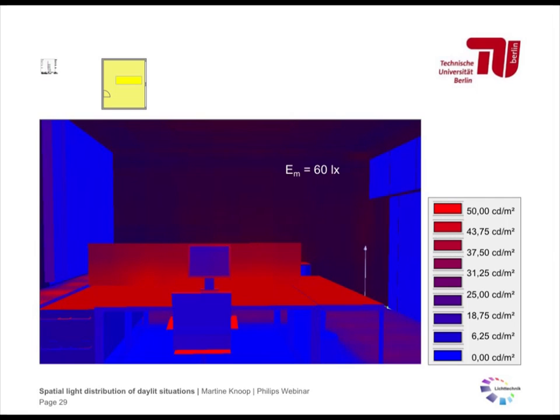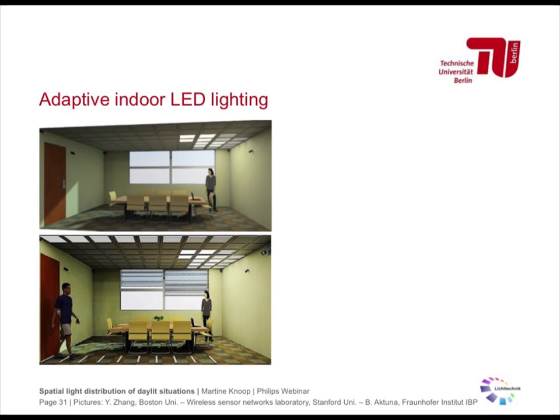I see on the market an advance of adaptive interior LED lighting solutions, or maybe not on the market, but definitely in research. And adaptive interior lighting solutions might really change this. So just keep in mind that if you have directed lighting, the luminance of the walls changes as well. So we have adaptive indoor lighting here. This is an example of it, and it shows that lighting is only used at areas where there are activities. So we have a general lighting level, and additional lighting is switched on or dimmed up only in areas where